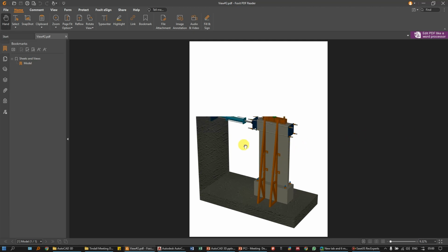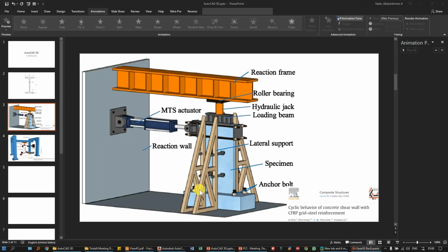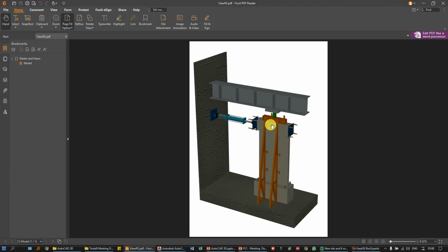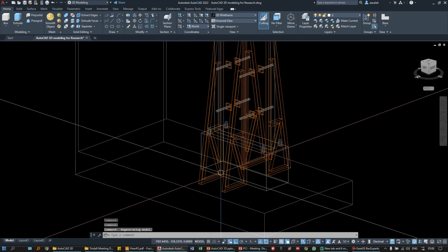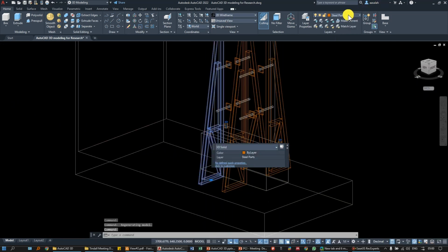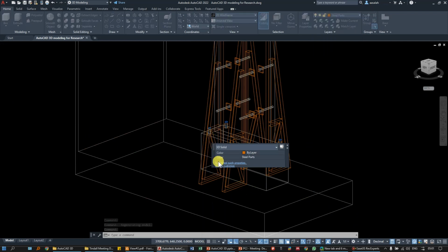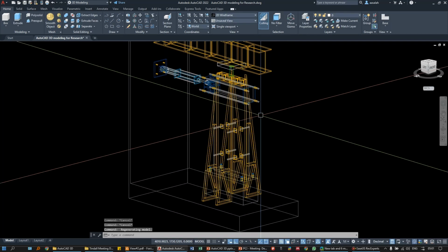Yeah, so this is the 3D model. As we can see, the material texture is not that good to present, but we can always keep using normal colors, which I will do now. I just want to show similar colors to this one because ours are a little bit darker. I can do that by changing the parts colors. Let me go back to this, and from here let's change it. This is the beauty when you use colors or when you use layers. You can always just change one color and it's gonna be changed all.